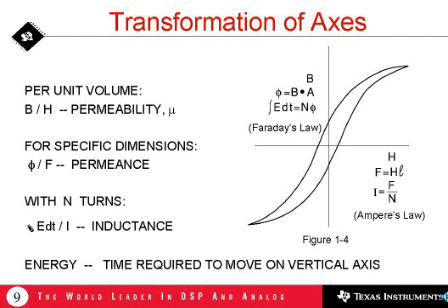If the field intensity axis, H, is multiplied by the magnetic path length of the specific core, then the field intensity axis becomes transformed into total magnetic force. So now we have a new set of axes, flux and force. These describe the hysteresis loop, rather, in terms of the specific core made of this material. The slope plotted on this new set of axes, phi over F, is what is called permeance.